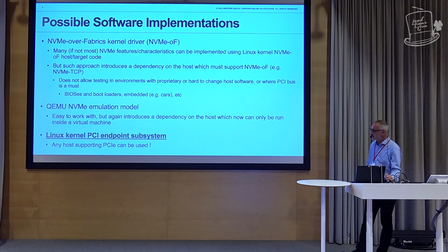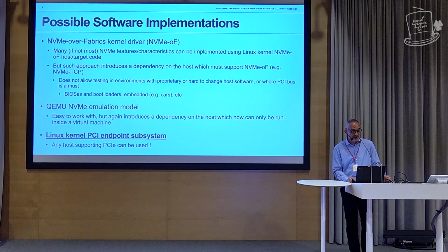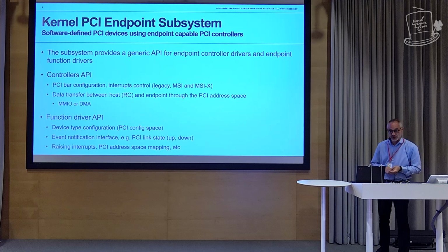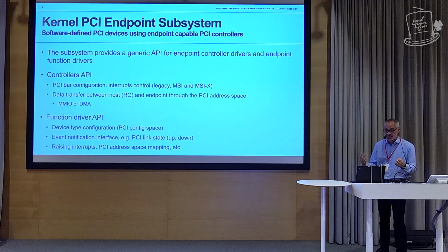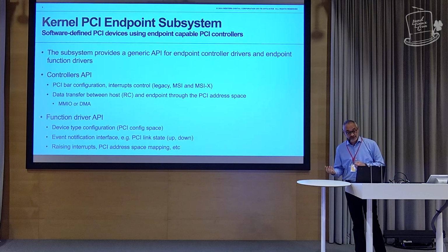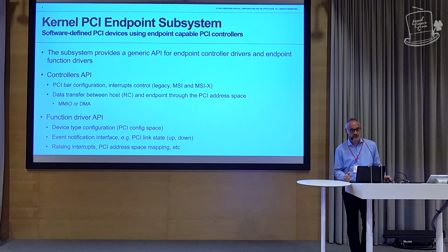But hopefully, we have the PCI endpoint subsystem in the kernel, which allows you to actually create PCI devices in software. So what is this subsystem? Essentially, there are two parts to it: two sets of generic APIs. One is to write endpoint controller drivers, and the other is endpoint function drivers, which plug into the controller driver to create a PCI endpoint.